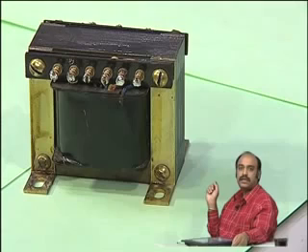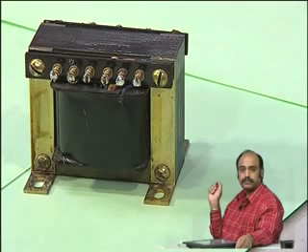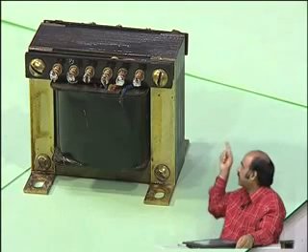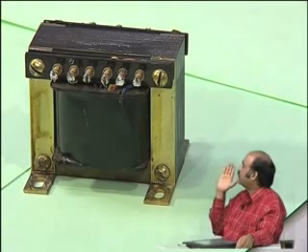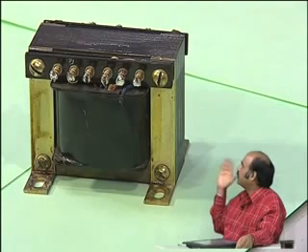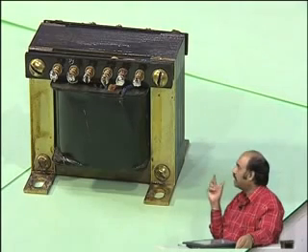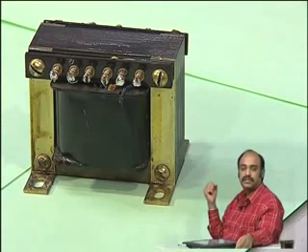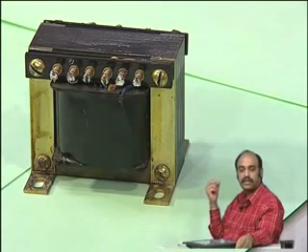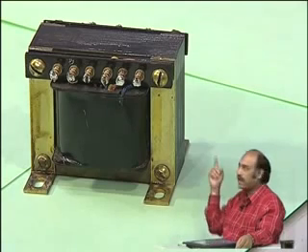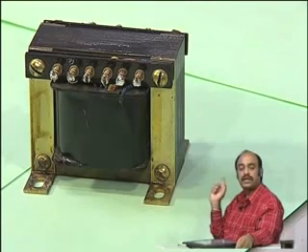So, to reduce the cross sectional area for the eddy current path and thereby increase the resistance for the eddy current path, the laminations have been put. All practical transformers will have the solid bulk of the core laminated, and then after laminating, all air pockets are vacuumed out and then it is varnished. So, that darkish color is due to the varnish.